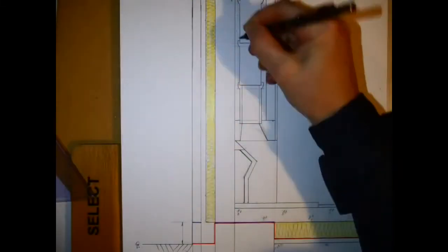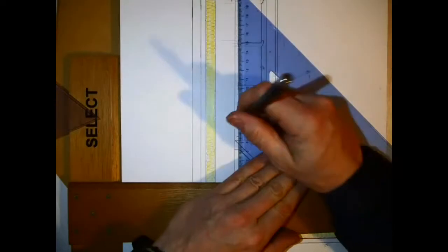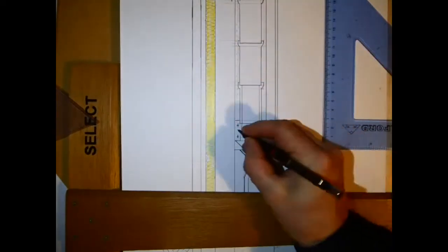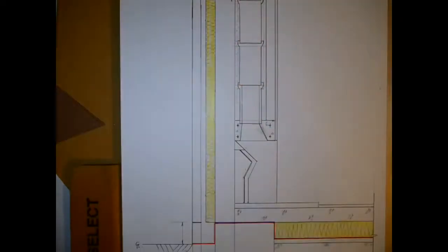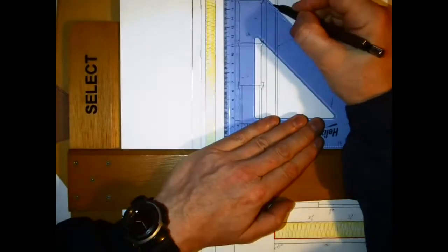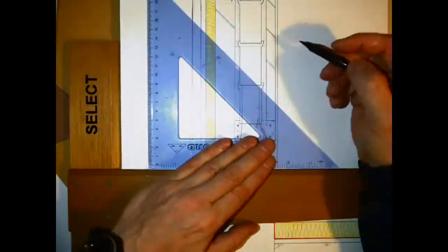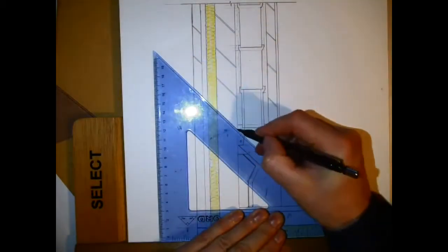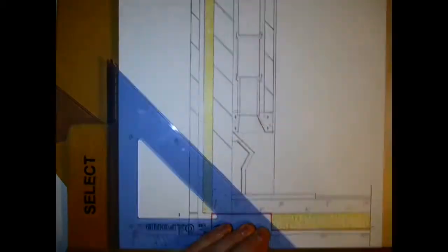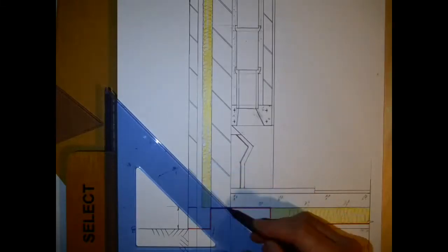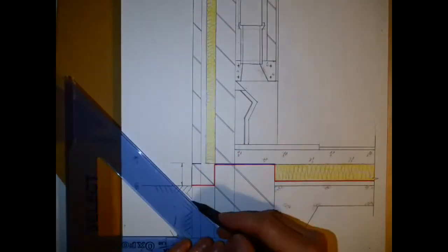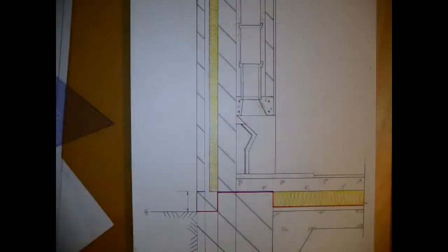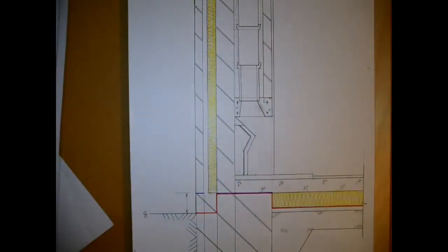It's more likely that you should have a fireplace on an internal wall, and you wouldn't have any of this design difficulty with where your DPM and your cold bridging would be, as you can see there in the lower part of the drawing. And other details, I'm just putting in a crosshatch for my blocks, because it's a hell of a lot easier to draw than trying to draw the arrangement of blocks in this here.